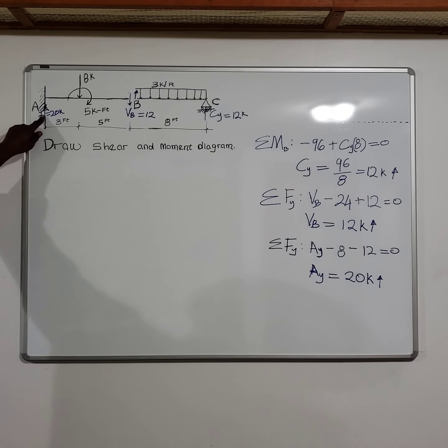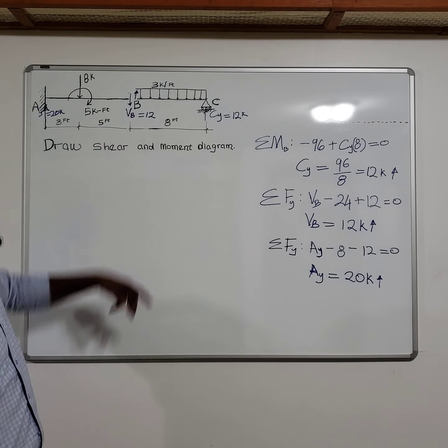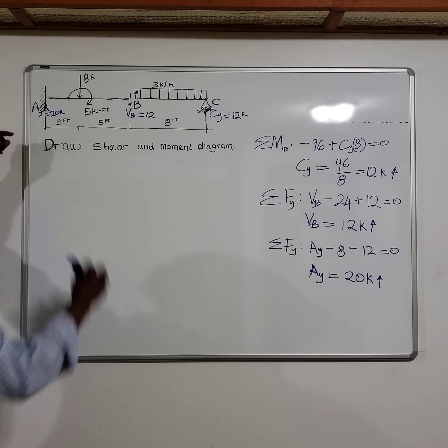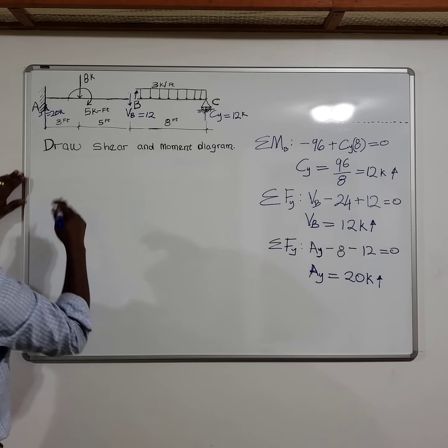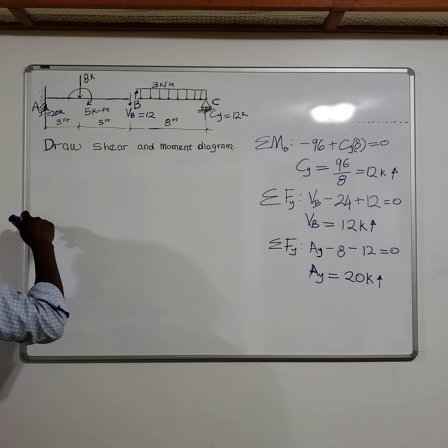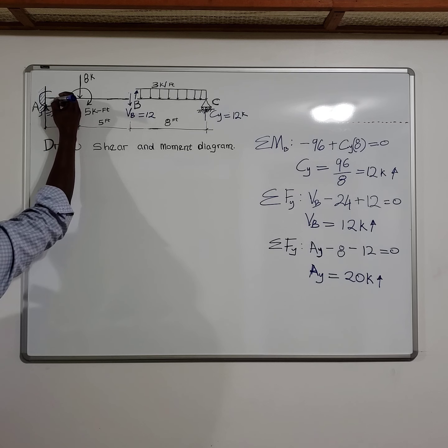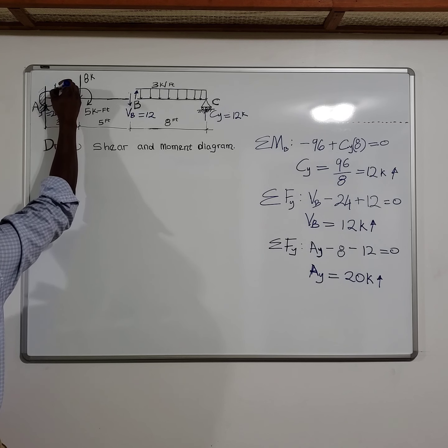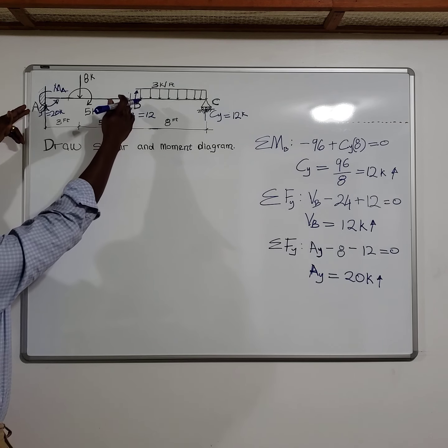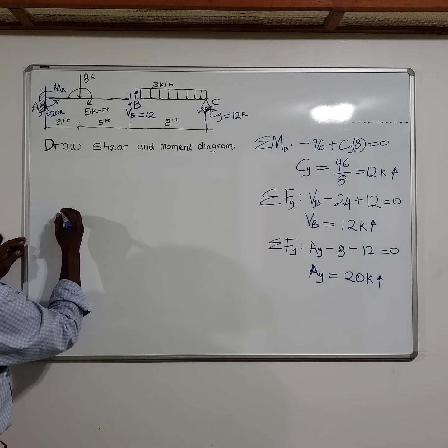All right, so we know that force. We know this force. This is an internal hinge. You don't really need it for your diagram at this point, but we know what it is. So now, what is the moment? The moment MA. So this moment here, let's assume this moment is a counterclockwise moment, MA, at this point. So let's sum the moment in this section to be able to arrive at the value of MA.